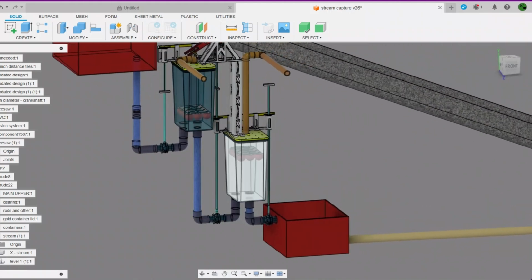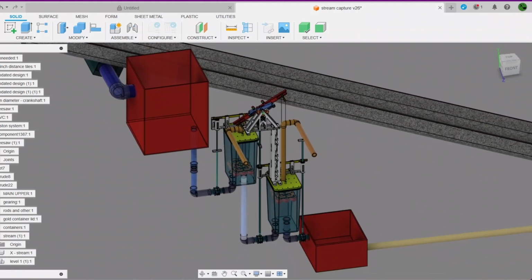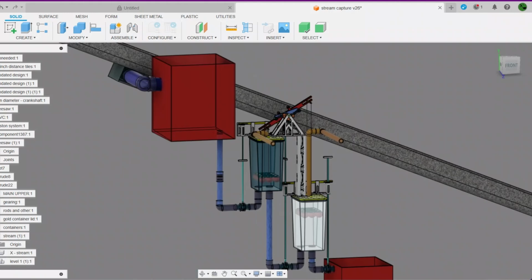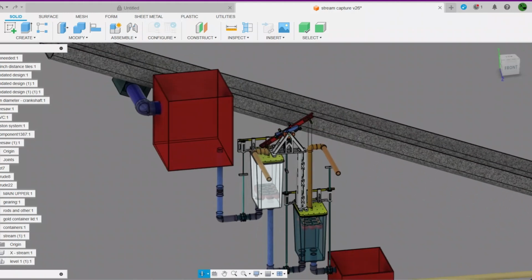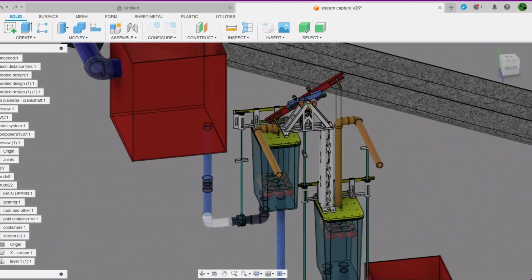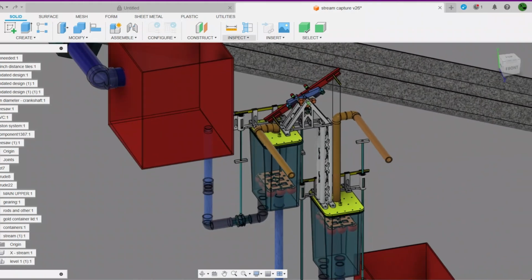When it's closed, then no water can get in, and you have another ball valve that then will divert back to here. So to start things off, there's going to be water in chamber 2 and no water in chamber 1. Now the ball valve is flipped, so now this ball valve is open.